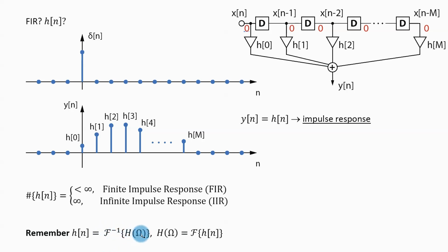And when you know the frequency response, this is how you can compute the impulse response. And when you know the impulse response, this is how you can compute the frequency response. And this actually gives you tools for analysis and synthesis of filters. If I give you a filter and tell you what its impulse response is, you can just compute